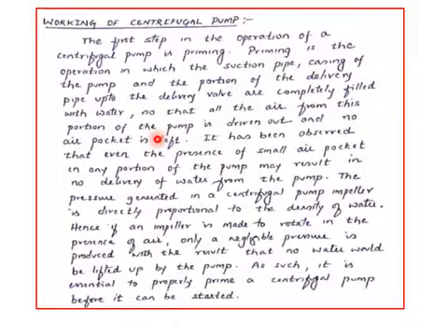When you start the motor, the impeller will do work on the water so that enough pressure head is generated. It is always essential to properly prime a centrifugal pump before it is started, so that no air pockets are left in the casing of the pump, in the suction pipe, or in the delivery pipe up to the delivery valve.